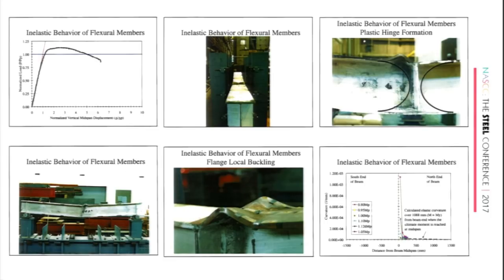What typically happens with our loading, with our specimens, everything, is that it's not ideal. So if the load is just a little bit shifted, or the specimen is a little bit not perfectly straight, you're always going to get, as you saw in that earlier picture, which was again one of my tests, one flange up and one flange down. You would get the local buckles, but they would always be in opposite directions, not this way.